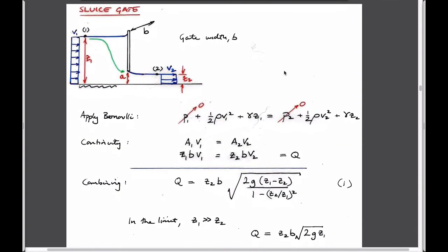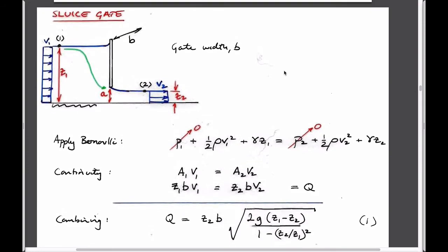So we have two free parameters out of our 3. We want to be able to measure velocity, v squared over 2g, to get velocity. We have a potential to measure pressure, which we can do with a pressure transducer, which is pretty easy if we have a confined flow. It's much easier if we have an unconfined flow to measure the z term. You could, of course, measure pressure. For instance, you could just put a pressure transducer on the base here, and that transducer would measure a pressure equal to unit weight times Z1, just a static pressure head.